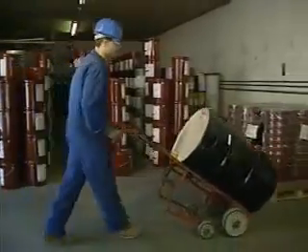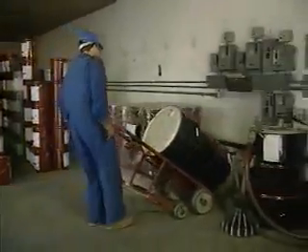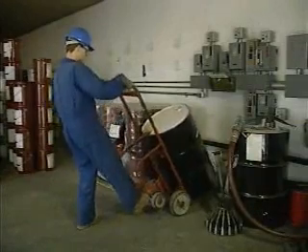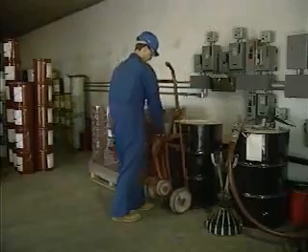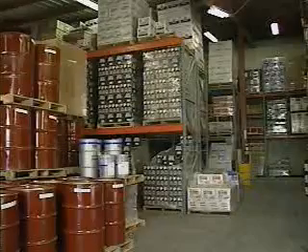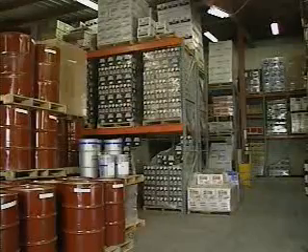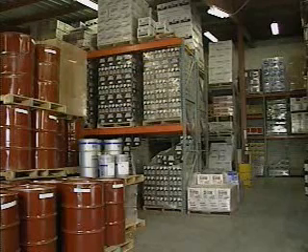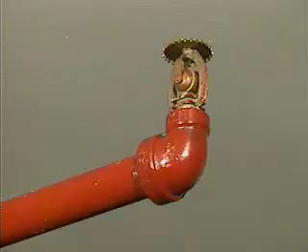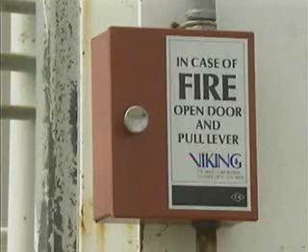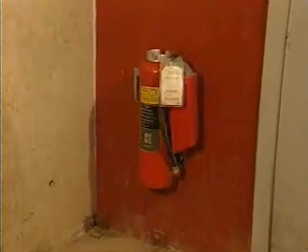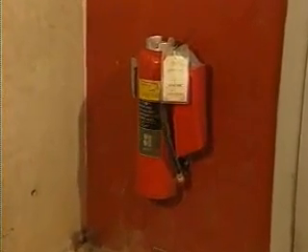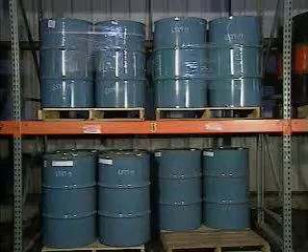When lubricants are stored indoors, weather is less of a problem than with outdoor storage. But contamination, spills, and fire are still hazards that must be dealt with. Store lubricants in a fireproof room or building that's clean, well-lighted, and well-ventilated. The storage area should have a fire extinguishing system that can be controlled manually as well as automatically. Also, keep an appropriate type of portable fire extinguisher in the storage room.